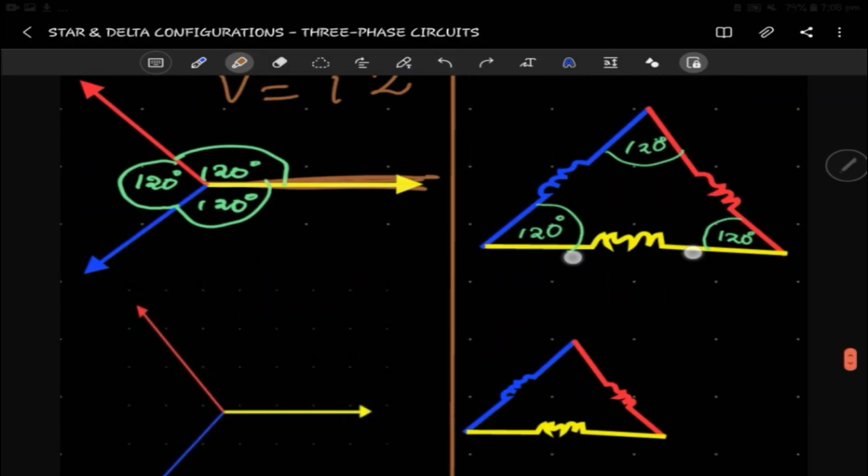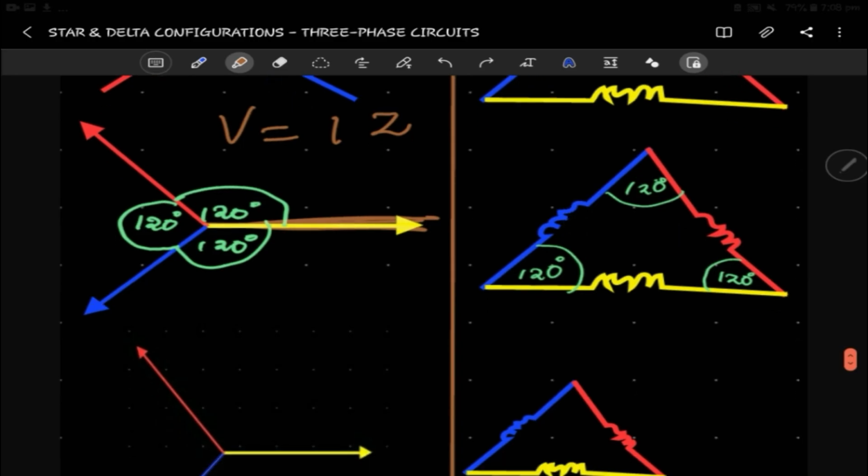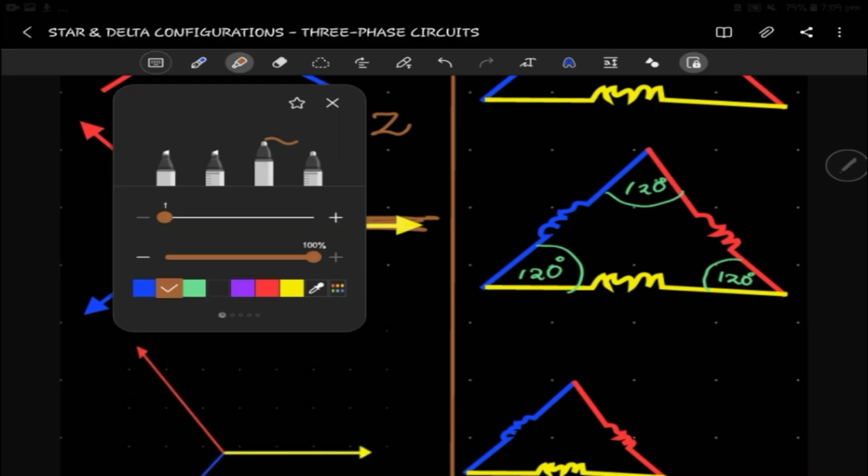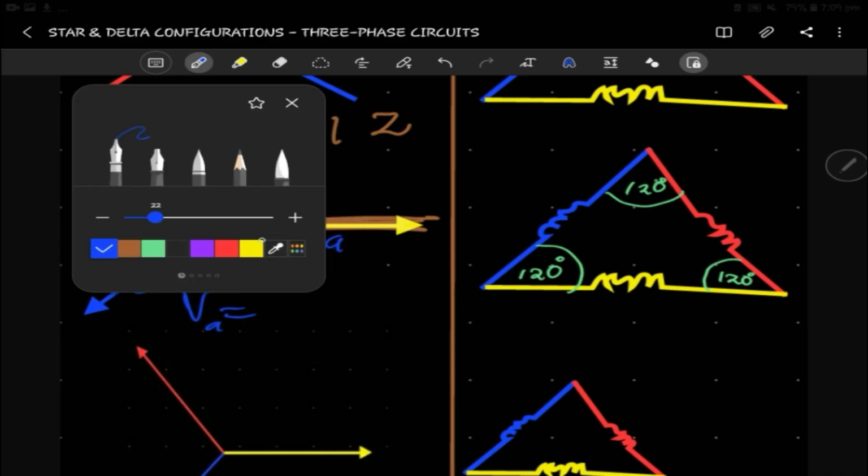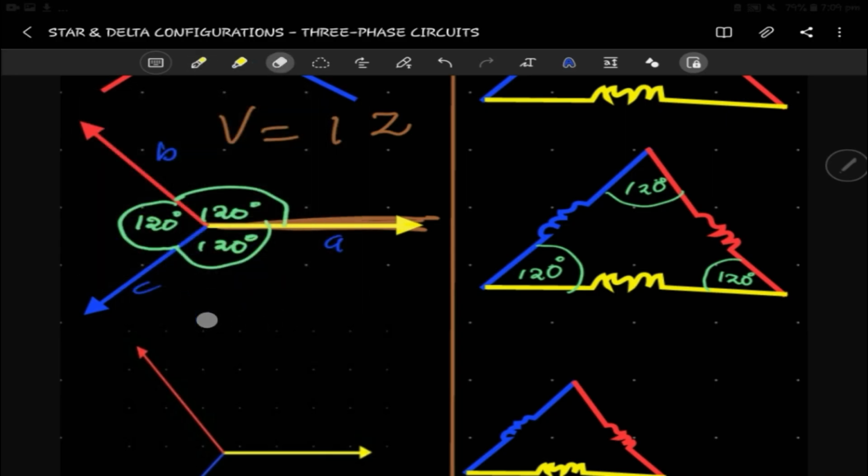And then when we're doing AC, we said that there are various ways for us to represent these phases. If this one is the reference, that will mean that the phase angle is 0. Because we are doing a voltage now, we can write something like V. Let's say this is A, this is B, and this is C. So this VA, the voltage in that particular phase, will be just the magnitude of it, and the phase angle will be 0, because it's the reference.